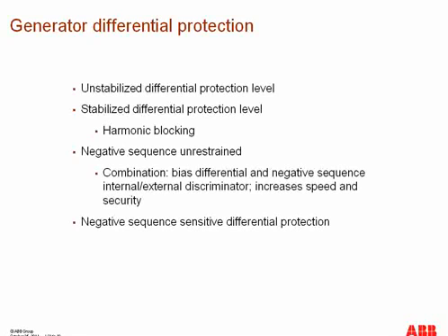For the stabilized differential protection, this protection can be made more sensitive, where the operation current is dependent on the stabilizing current. The largest measured phase current is taken as the stabilizing current in our ABB philosophy.